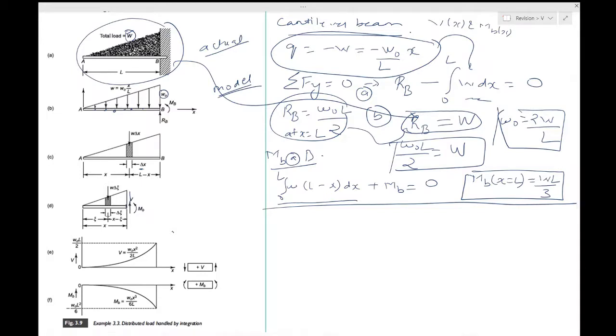Now E starts from here and goes until the middle, and hence this part is called delta E, and the remainder part would be x minus E. You want to now do this force balance. That would be V minus the integral from 0 to x of W dE equal to 0, and this is just the forces in the y direction.